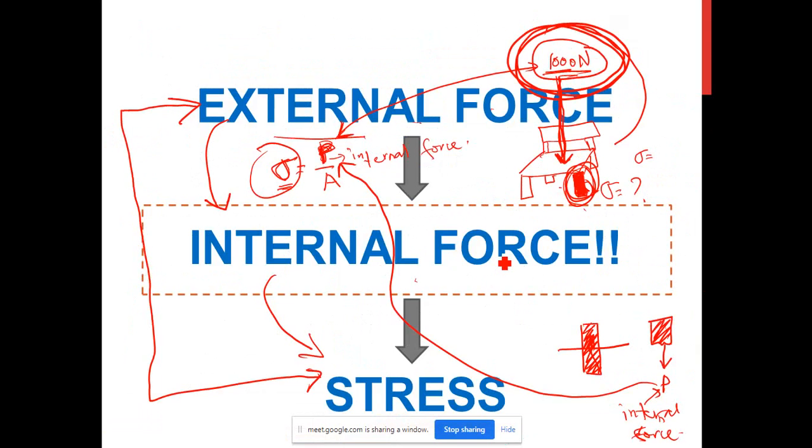And then as I said, in order to calculate the stress, the value of force that we will use is the internal force. Normally in the question they will give you the value of external force. So what you have to do is a static analysis in order to calculate the internal force, and then using the internal force, you can calculate the stress.